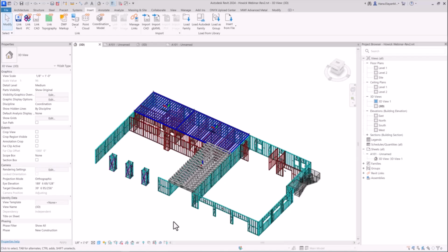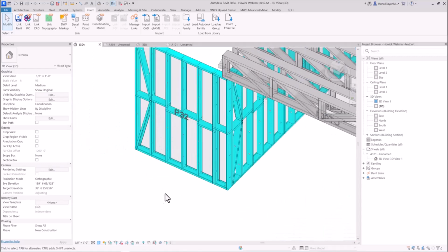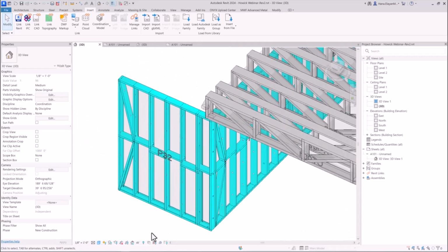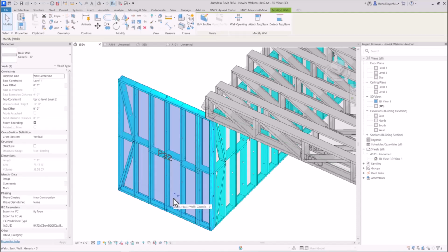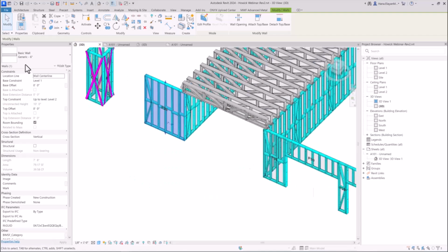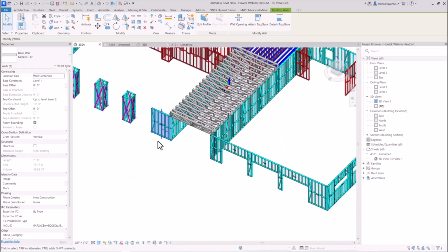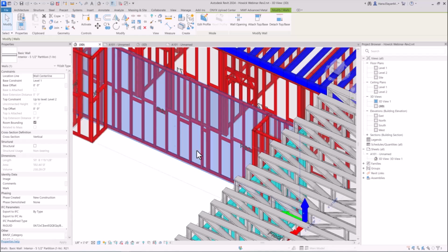Now let's talk about adding these families to our panels. Let's start from scratch. To start, you do have to have your model ready. I've already created my project using specific wall types, generic wall types that you can find in about any regular Revit template. I'm using this specific wall type for the exterior walls, and I've used something else for the interior walls over here.